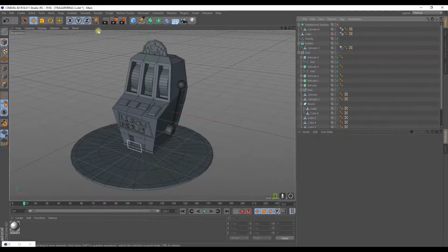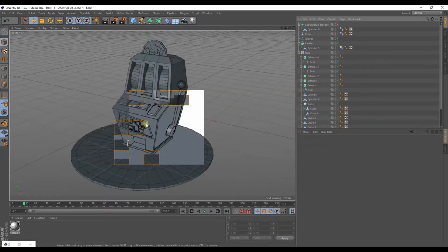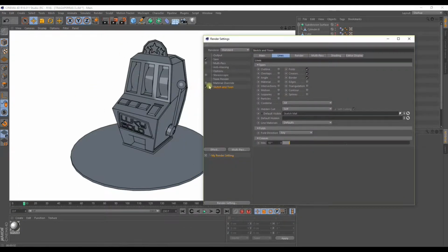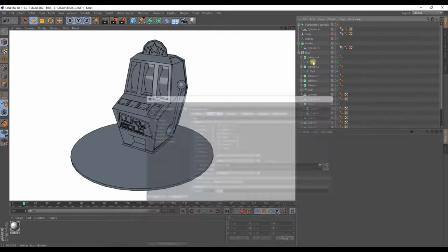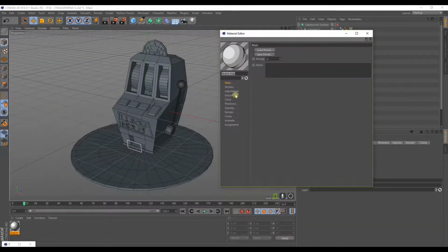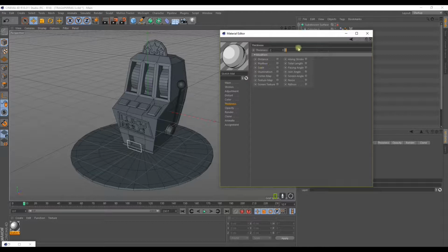If we activate the Sketch&Toon box though, we're going to get a cartoon effect, okay? So the edges look as if they're drawn in. Everything does, okay? And the color and the shades look like they were done in a vector program, like Illustrator. Once we've activated this box here, we're also going to get this material here. And from this material is where we're going to be able to modify the lines, okay? Like the thickness.